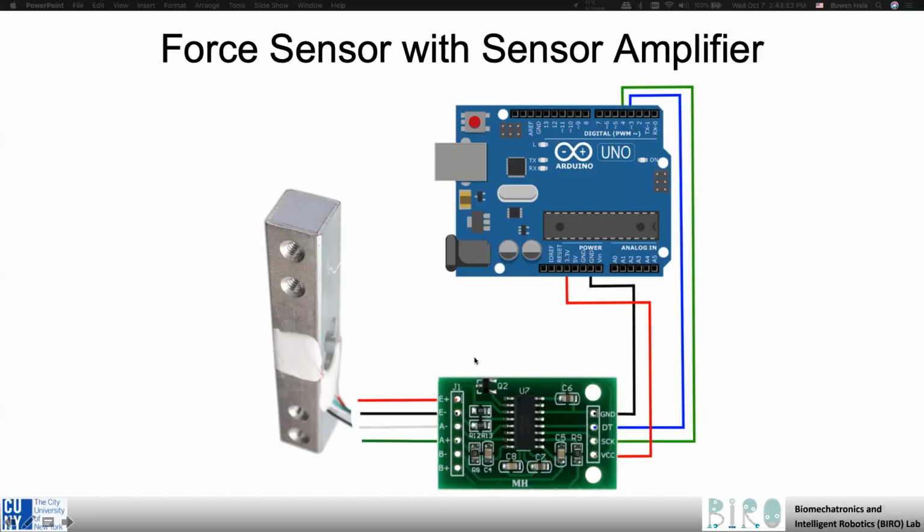By the way, quick question. For this force sensor to be hooked onto the sensor amplifier, how is this wired? It looks like it's supposed to be soldered on. Are you going to solder it for us when sending it out? No. You're going to use this male-to-male jump wire to connect them. Oh, jumper wires will work for this?